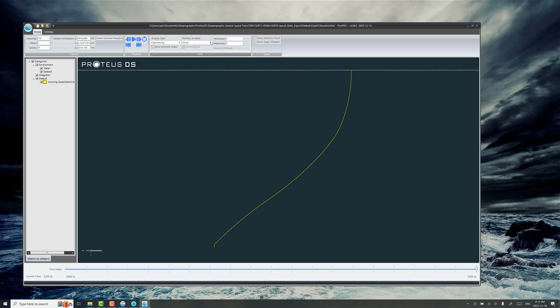So if you like, you can show the tension here. This is what I'd expect to see is higher tension up here where the buoy is. We've got the wire rope section here, everything goes down to basically very low tension where the fiber rope is, and then we've got a lot of glass floats to assist in recovery. So that's what the little knee is here in the higher tension region down there. So that's looking good. You could run the report tool now if you wanted to, but what I want to do is stay focused on setting up the dynamic load.